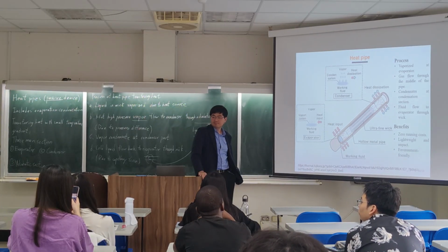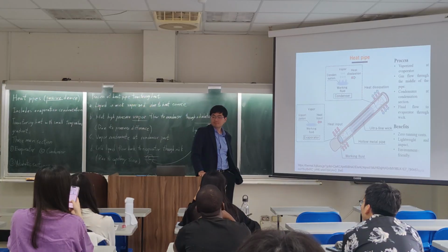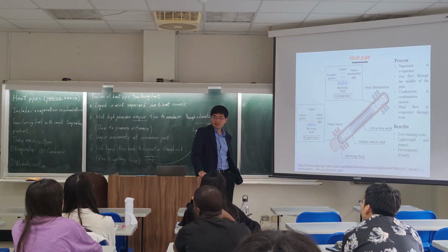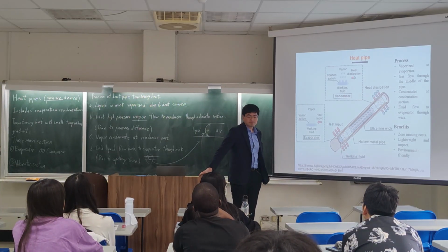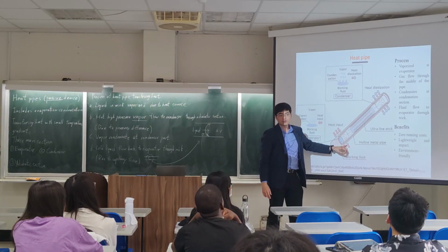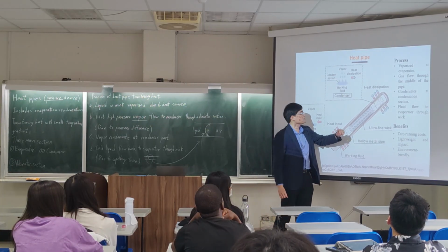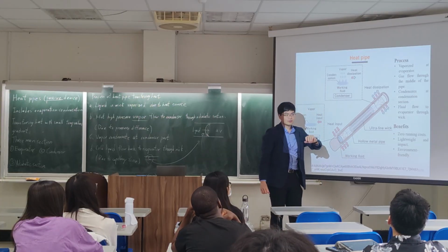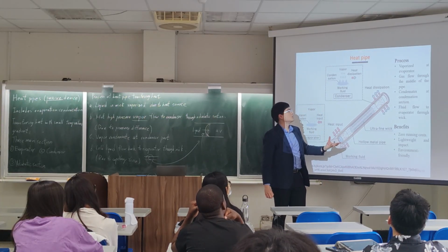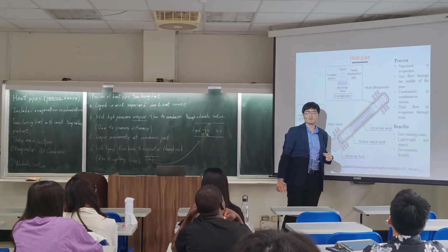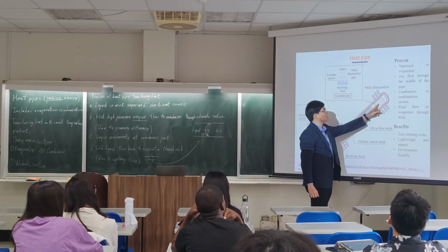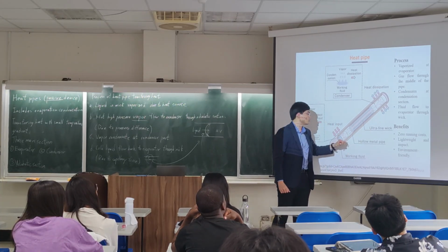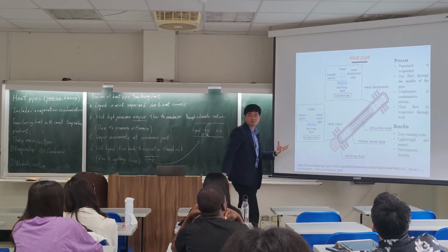Okay, you think choosing a better one. So one of the most important things is, like what he said, the heat dissipation in here must be good. You can improve the heat dissipation to improve the overall heat transfer efficiency, because more vapor is transferred to liquid, which means more liquid in here to evaporate.